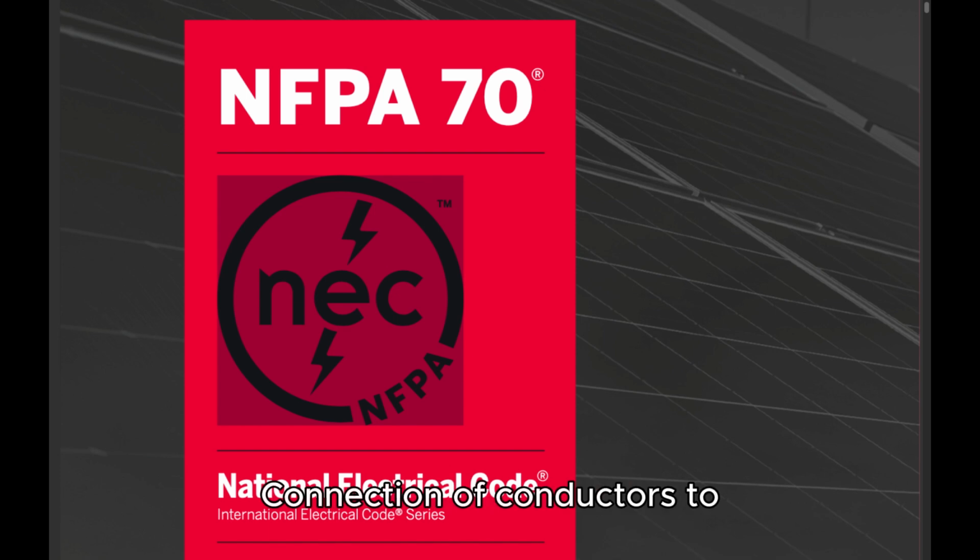A. Terminals. Connection of conductors to terminal parts shall ensure a thoroughly good connection without damaging the conductors, and shall be made by means of pressure connectors, including set-screw type, solder lugs, or splices to flexible leads.